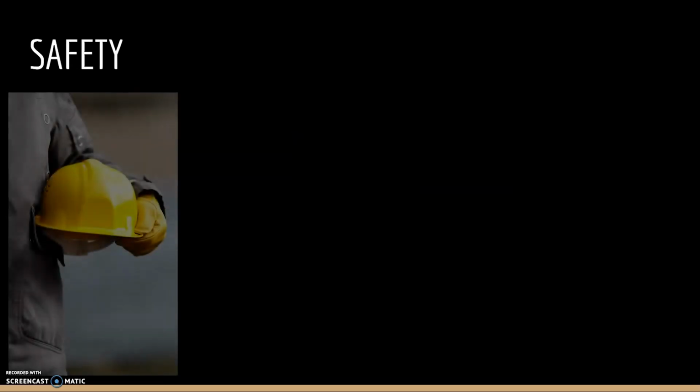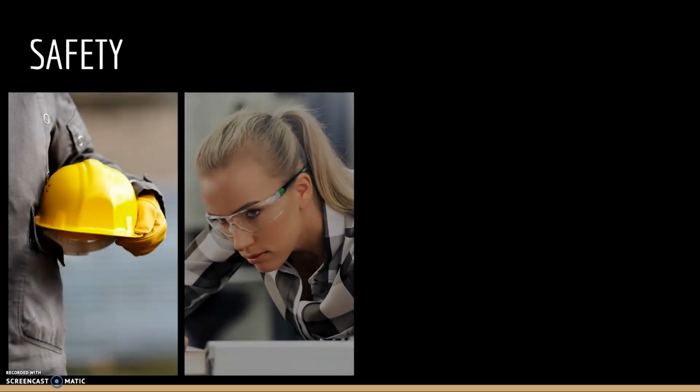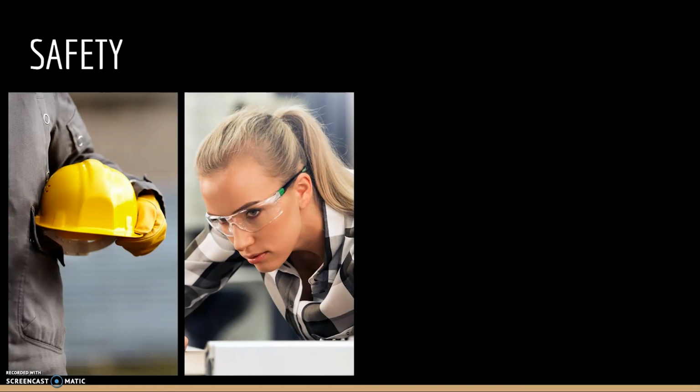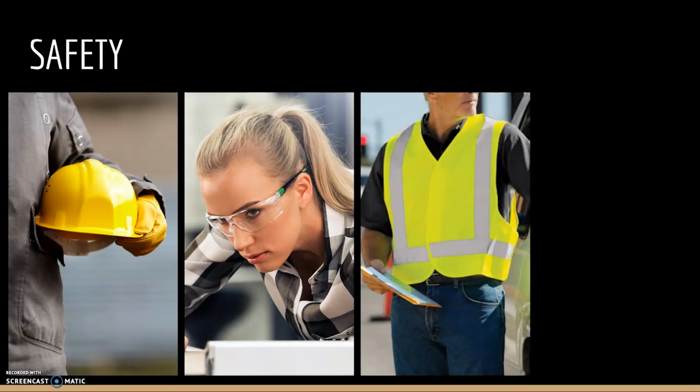From here, we'd like to talk more about safety, another overlooked aspect of project management. So as for safety on the site, the minimum requirements for PPE are as follows: a hard hat, safety glasses, a reflective vest, and steel-toe boots. Additional PPE is required for certain activities and noted in the JHAs located in the Construction Safety Plan.